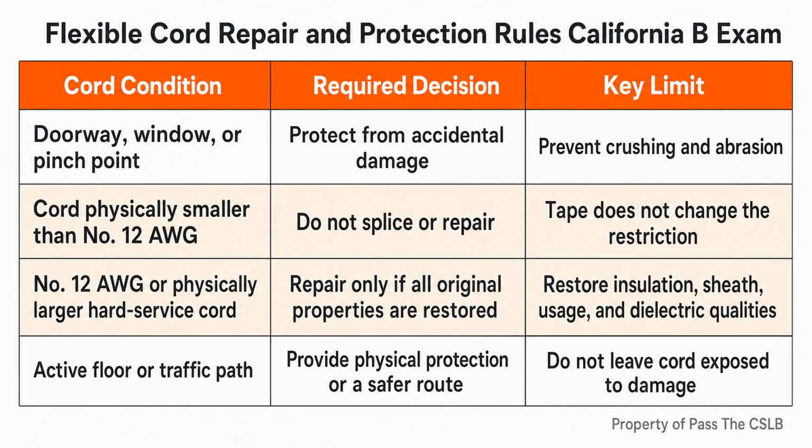A tag that only says danger or do not operate does not carry the full required information. Lockout is the primary physical control when the disconnect can accept a lock. The tag communicates who applied the control, why it is there, and when it was placed. I remember the 3 tag facts as a reason, person, date. That short sequence keeps the information practical without turning Lockout into paperwork theater.